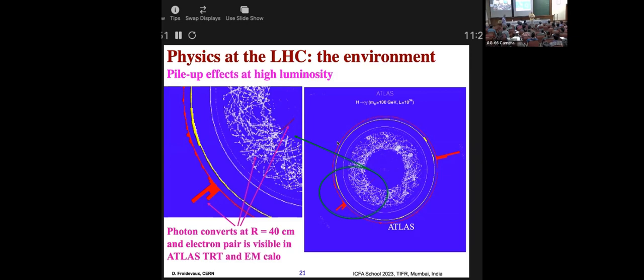Then I think a further answer to your question is that we knew that most of the detectors would die gracefully. For example, in a silicon detector, what happens with radiation? Its leakage current goes up. And for this, you have a power supply which you've designed to let it go up and still provide the power such that it will work. But then you have intrinsic things which happen with the behavior of the silicon, and you lose efficiency to collect the electron pairs.